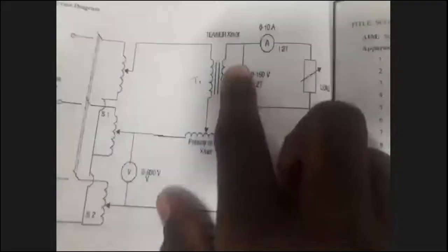And one voltmeter can be connected to measure the supply. Similarly, on the secondary side, for the teaser transformer, one terminal of the teaser transformer can be connected to the ammeter, one terminal. The next terminal of the ammeter can be connected to the load, one terminal. The next terminal of the load can be connected to the transformer 100% terminal. And one voltmeter can be connected across that to measure the secondary voltage.